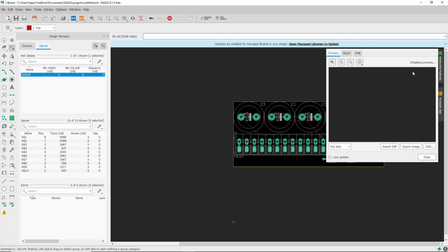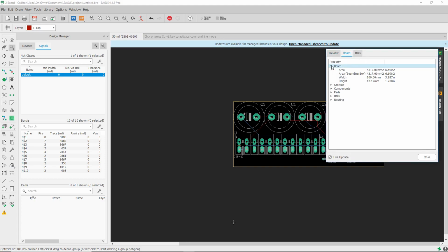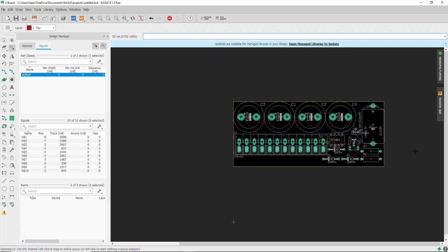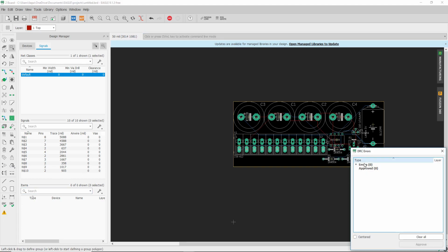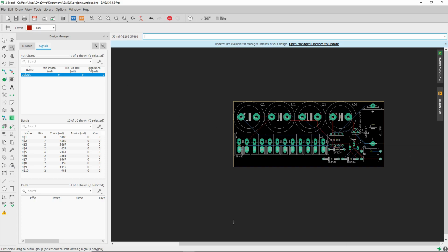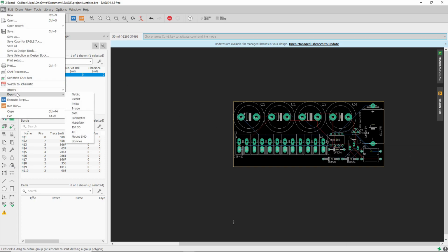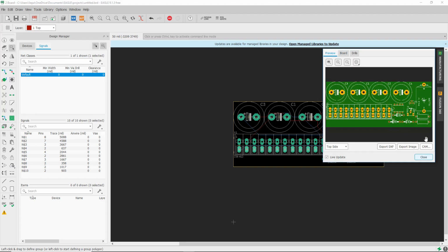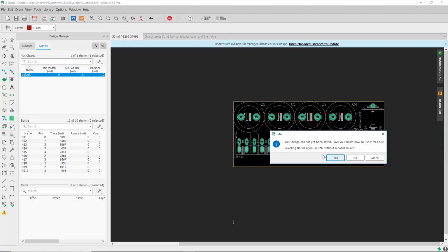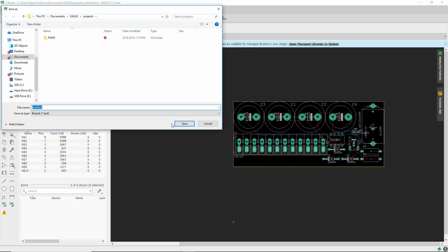After the Auto Router is done, all you need to do is you go to either File, Export, or Manufacturing CAM. This is how you export the Gerber files, and this just allows you to send off your board's design for creation by any studio you want.